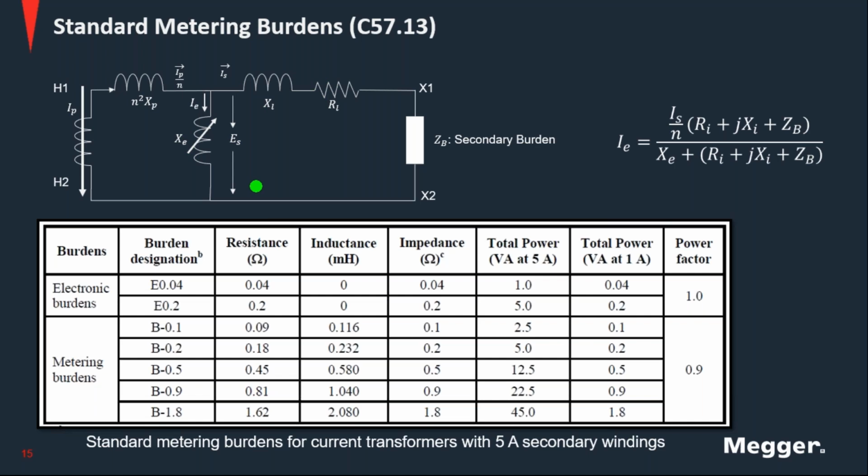This is the CT or the VT, we can have the same thing for a voltage transformer, but this will produce a voltage or a current at these terminals, and this burden cannot exceed certain limits, because if not, it is not going to perform as specified. So that's what we also have from the standard. We need to guarantee that the burden connected to this instrument transformer is not exceeding these limits.